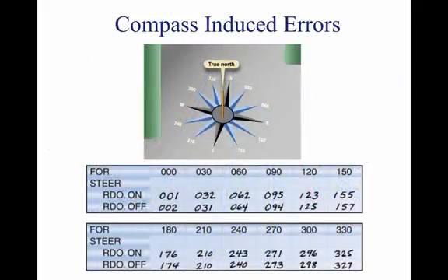The magnets in a compass align with any magnetic field. Local magnetic fields in an aircraft caused by electrical current flowing in the structure, in nearby wiring, or any magnetized part of the structure conflict with the Earth's magnetic field and cause a compass error called deviation. Deviation, unlike variation, is different on each heading, but it is not affected by the geographic location. Variation error cannot be reduced or changed, but deviation error can be minimized when an AMT performs the maintenance task known as swinging the compass.